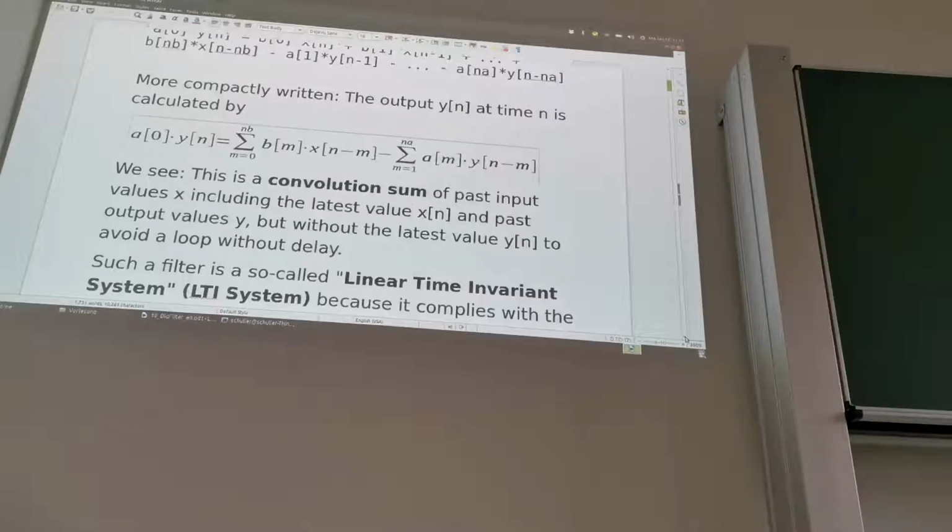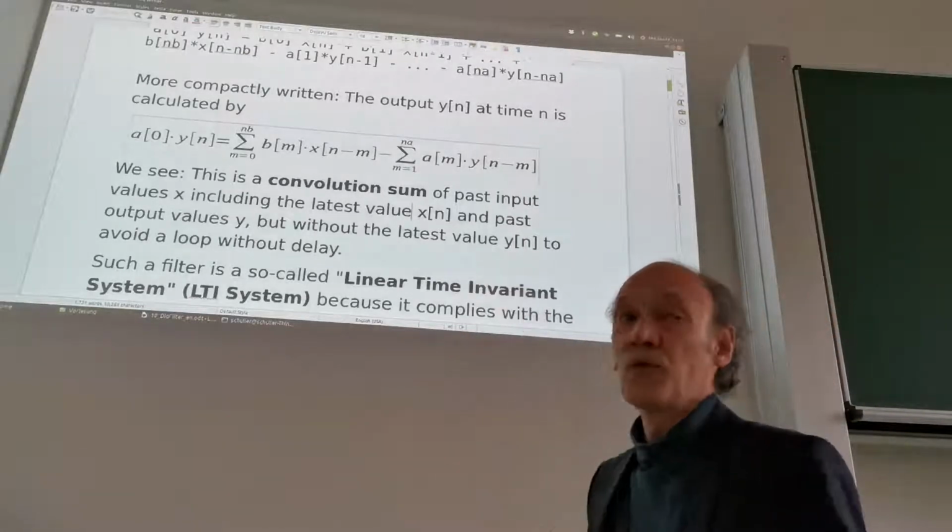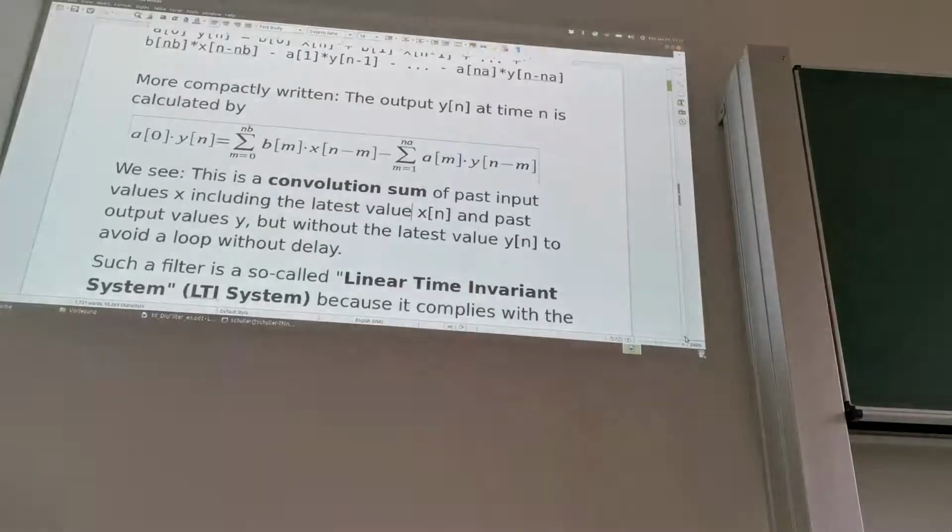So two convolutions, and convolution is something that we already saw when we went from the FFT or the DCT domain back into the space or time domain, when we applied our mask. The mask was element-wise multiplication in the frequency domain. And element-wise multiplication in the frequency domain is convolution in the time or space domain. So here you can see that indeed now we have this convolution that we saw from our filtering process. So, makes sense.